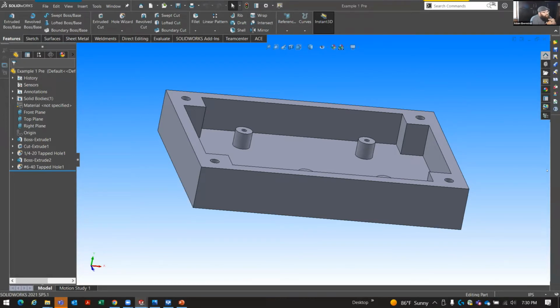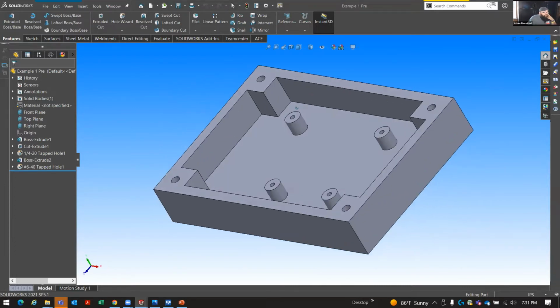Yes. That's all things that have got to be considered when you're making a design. And this is a lot of things we run into with new hires or people who just haven't been explained really well, or somebody who's not had machine shop experience. They know, okay, well, this part gets it done. It's quick. It's dirty. It's on the floor. Now, if I was to pick this part up and it was made exactly like this, it'd be kind of dangerous to handle, wouldn't it? Sharp edges everywhere, probably burrs all over the place. It'd be difficult. So how would we go about making this?